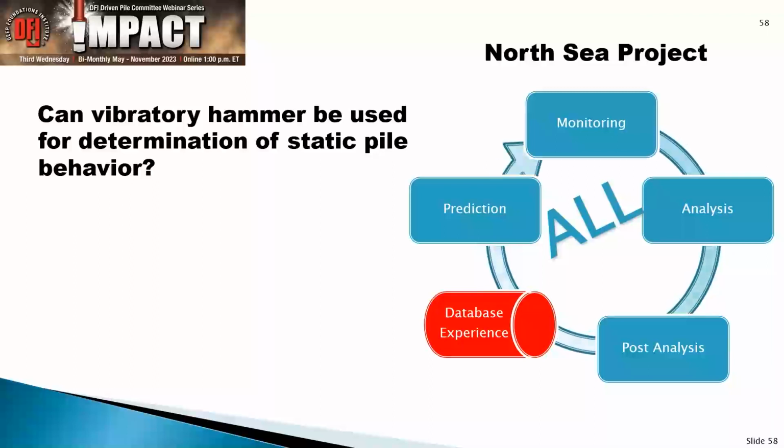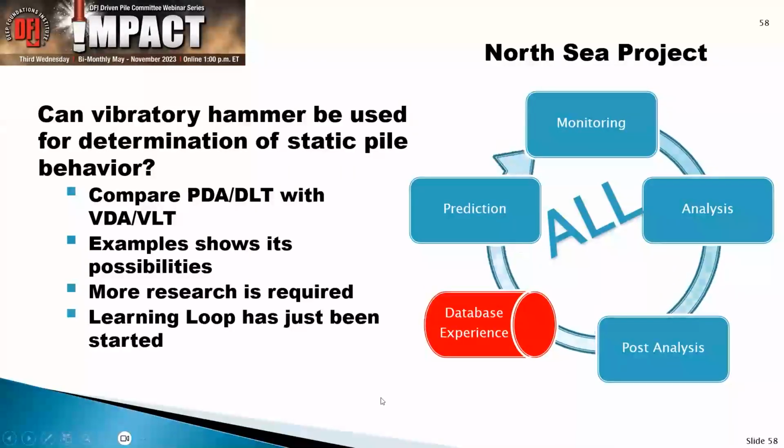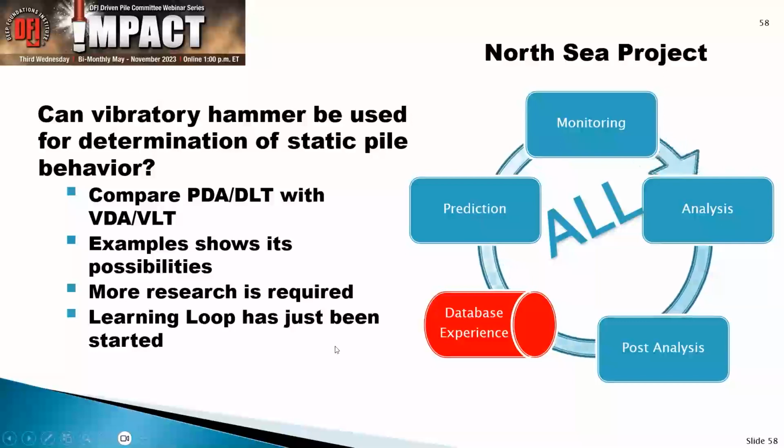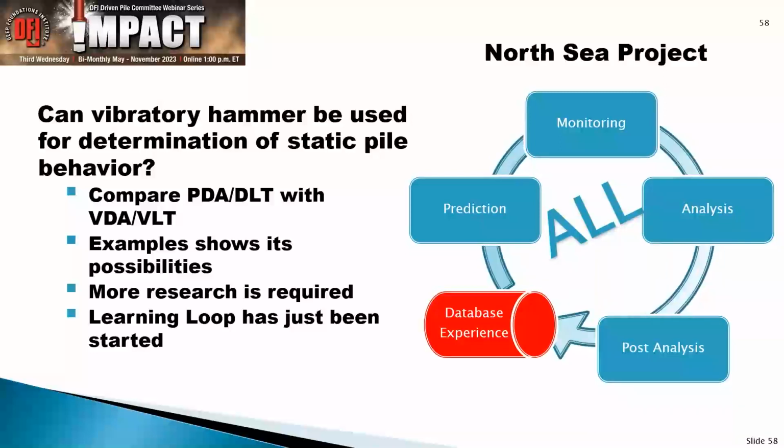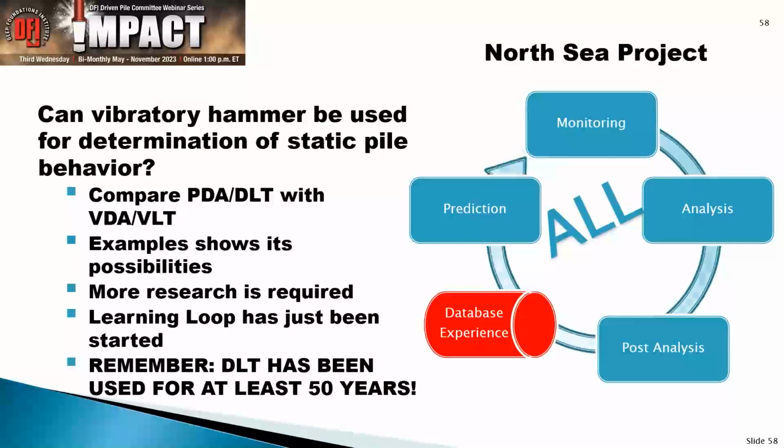So can a vibratory hammer be used to determine the static pile behavior? Because quite often right now we still have the situation that we insist that a vibratory pile that is load bearing, the final couple of feet is driven with an impact hammer. Well, the more data we're going to get, it definitely has potential. The only thing is, this database that you see there, the red tube, is not yet as full as you have it for impact driving. So that's something where hopefully after you hear this presentation, we feel a lot more comfortable with this whole thing.